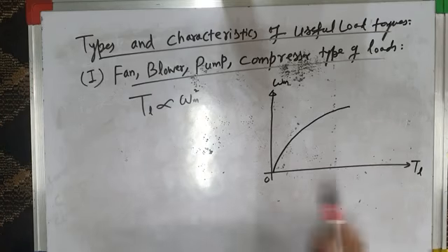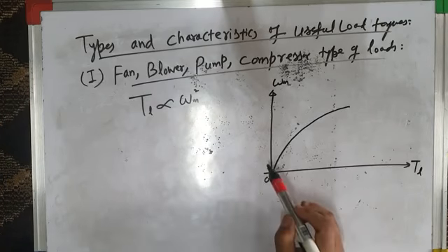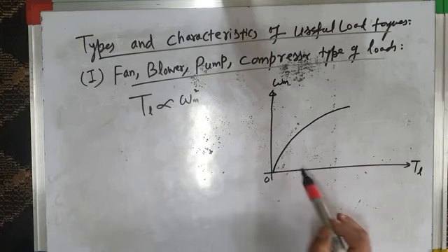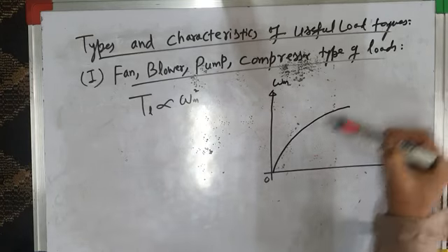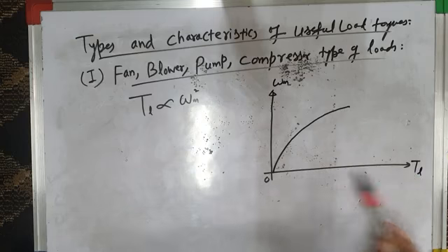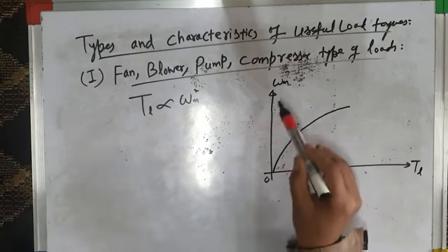So this is the load torque characteristic. You can see the torque is proportional to the square of the speed. It's not a linear relationship. It's a non-linear relationship. Torque is not proportional to speed. It's proportional to the square of the speed.